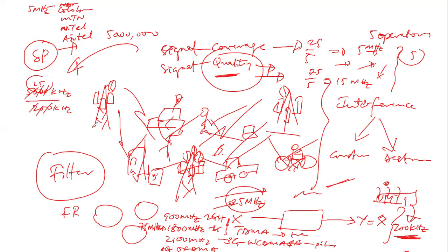So this is what we can assign to a particular cell. That's why we now have automatic radio frequency numbers, so that each of these frequencies is assigned a number, say 1, 2, 3, 4. Then if we have XYZ base stations in this particular cell, the frequencies assigned here are limited, so they have to be reassigned somewhere in another channel. That's why we do frequency reuse.